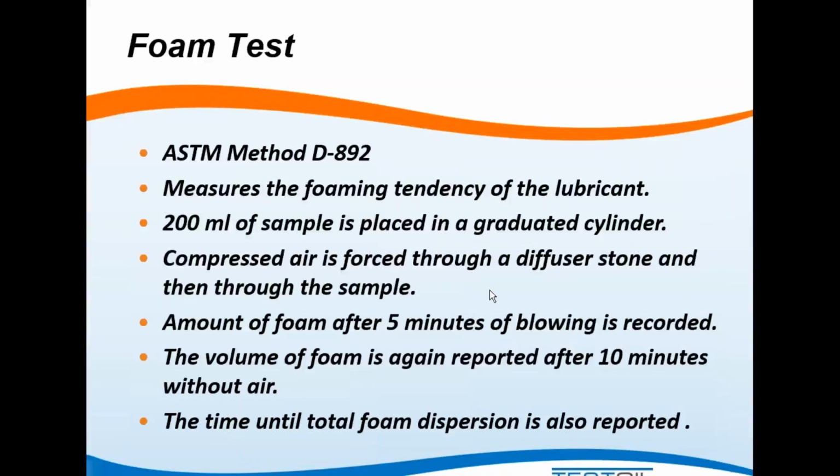How much foam did it generate during those 5 minutes, and then we'll monitor the amount of foam, and the test is over either at 10 minutes or when all the foam is dissipated. So a lot of times, when I'm taking a look at the reports, you've got to remember we're purposely putting air into the oil, and in general, inside your machine, unless you've got a mechanical issue, which a lot of times foam tends to be, you're not purposely putting air into the oil.